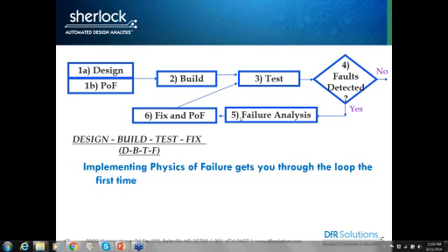Really, what you're trying to do with any type of burn-in is screen out defects. One thing that is usually good at screening out solder defects is a few severe thermal cycles, minus 40 to 125, 4 or 5 cycles. A high or elevated temperature screen can look at a defective component if there are any die issues.